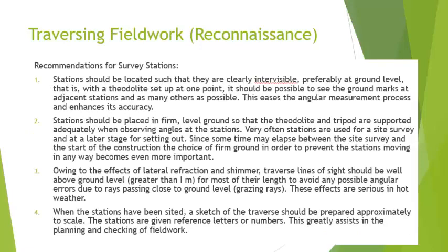There are some recommendations for the selection of survey stations during reconnaissance. The stations should be intervisible to ease the angular measurements. Stations should be placed on firm ground. The traverse line of sight should be greater than 1 meter in height to avoid lateral refraction and shimmer.